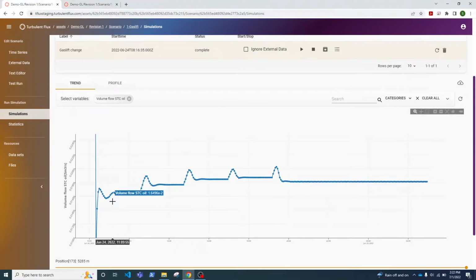What it means is that when we are increasing up until a certain point, the flow is gravity dominated, and injecting more gas lift into the system actually helps in reducing the density of the column. But as we increase it further, it goes into friction dominated flow, so then it's giving less oil rate. It's not helping much. So that's why it's always important to find the optimum gas lift rate for the maximum oil production.